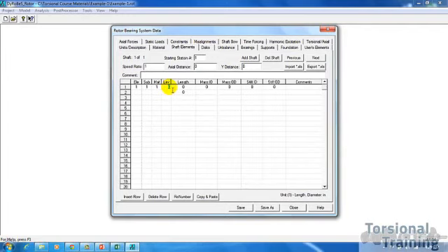Now you type 0, because what the level tab does is it actually gives you a vertical distance. In this case, since we're building a simple shaft, we're not going to be adding any shaft above or below the shaft that we're working with, so ignore that and leave that at 0. Our example shaft is going to have a length of 10 inches, and leave the mass ID, which is inside diameter. Since we're modeling a solid shaft, there's no inside diameter, so in this case the mass inside diameter is 0. Now the mass outside diameter, make that 8 inches.